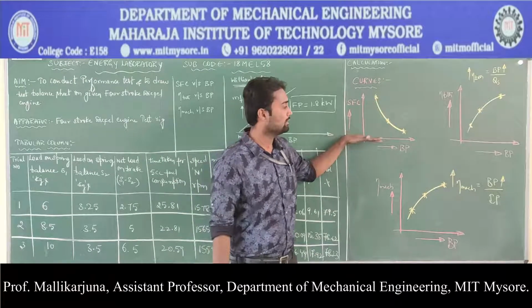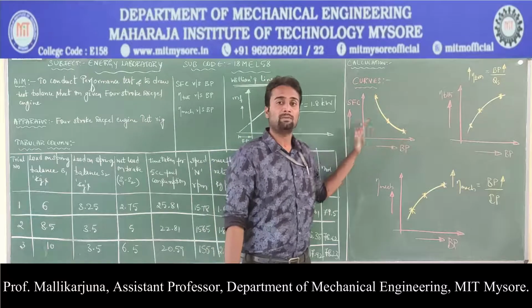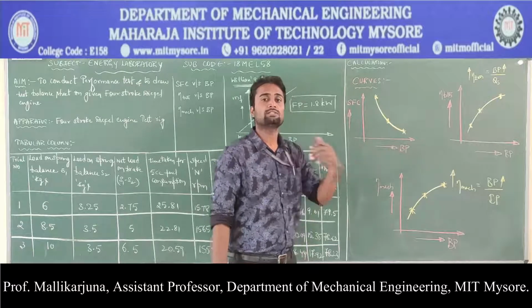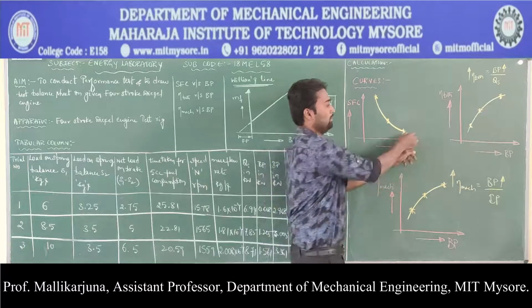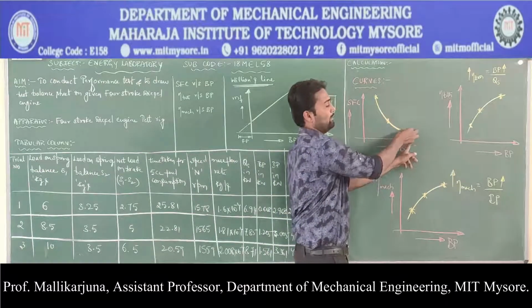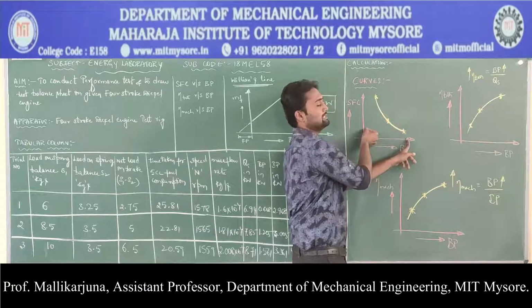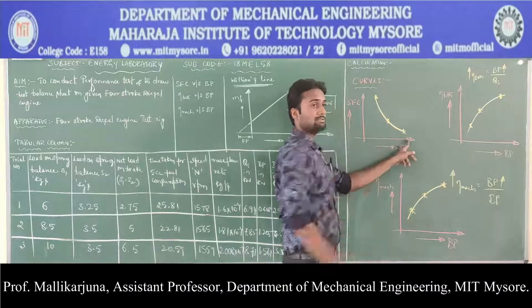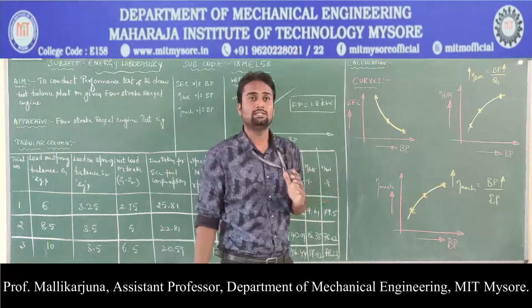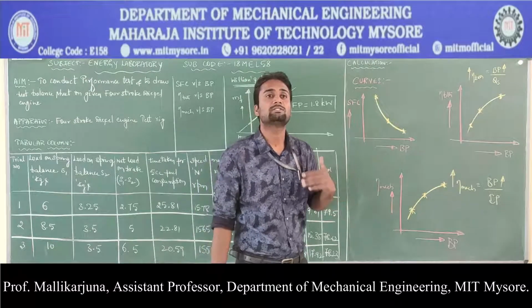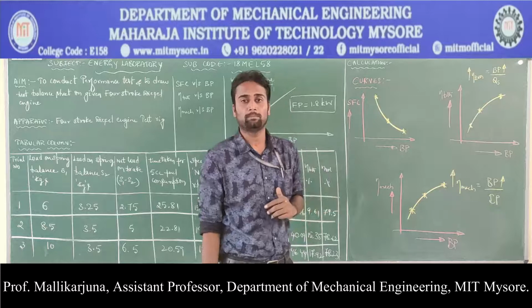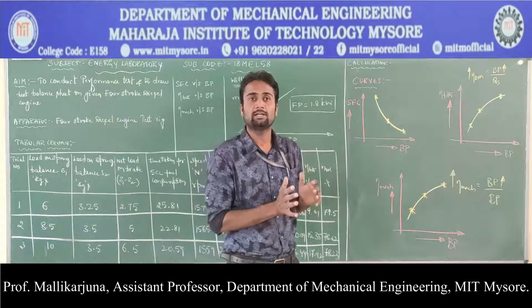As you move on running the engine, once the engine takes the momentum, if you look on to the same 1 kilowatt power development, the specific fuel consumption is less. In the sense, fuel consumption by the engine goes on reducing as the engine gains the momentum. At the very initial state, it is higher.